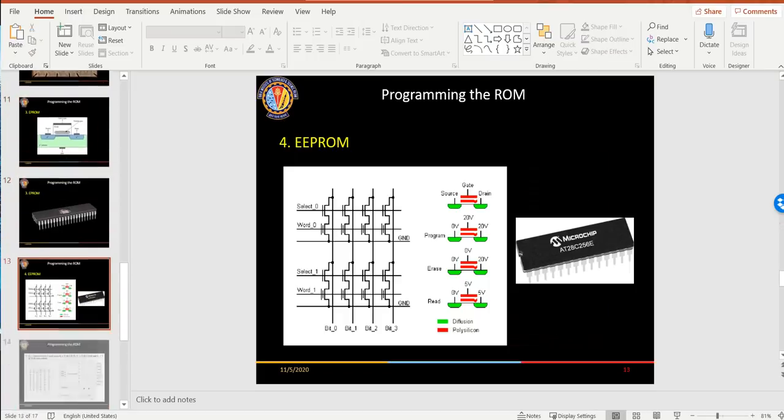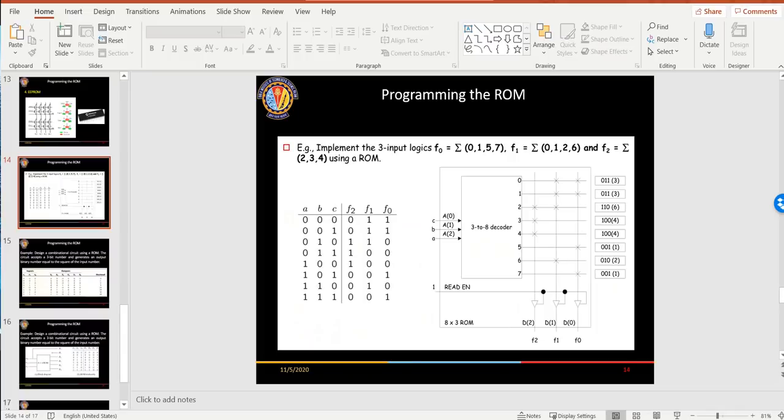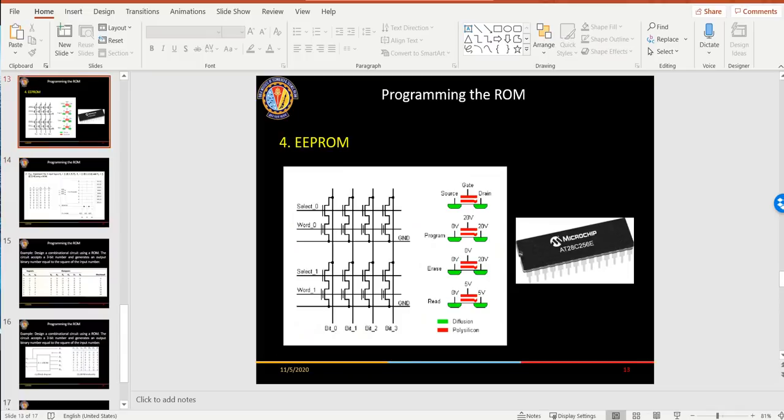Similarly, when we saw the EEPROM, I said these are the EEPROMs where you have these links. There are vertical lines and horizontal lines running here, and each crossing can be connected by giving an appropriate voltage during programming, so that they make permanent connections. If you give a very high voltage, some charges will be trapped on the floating gate.